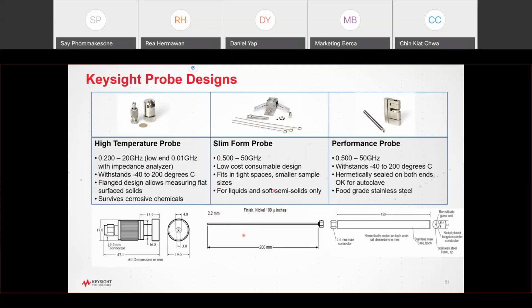When you order this probe, it comes with 3 calibration standards. This is the short standard. With this particular probe, since the gold piece here makes contact with the probe, it may not give you good contact. So we highly recommend inserting this conductive disc into here when you do the calibration.